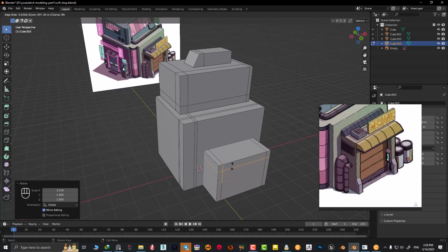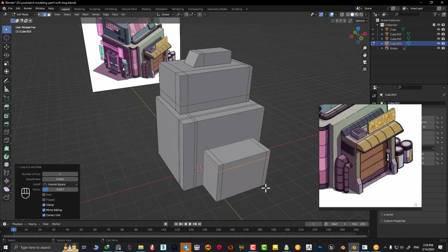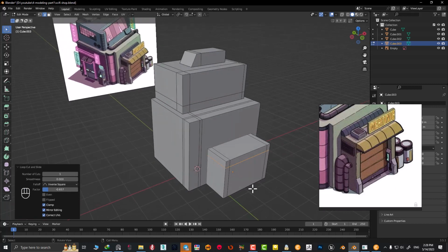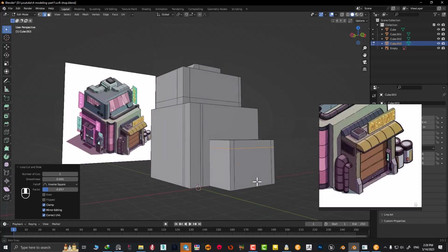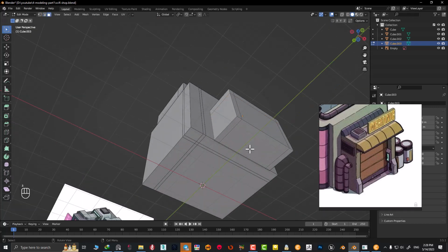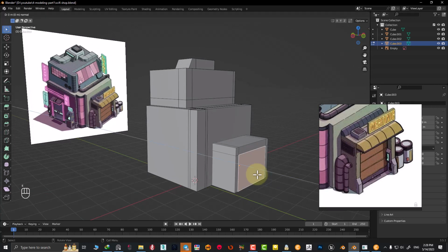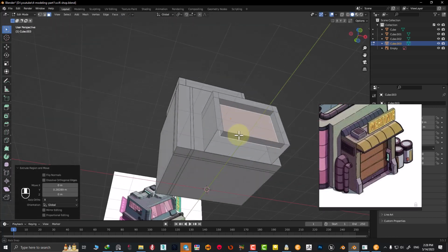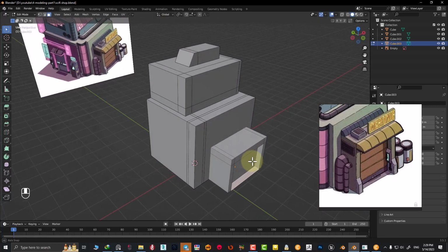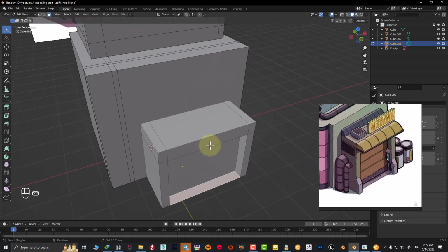Next, we want to remove the faces at the bottom because we don't need them. To do this, press 3 at the top of your keyboard to select polygons. Hold Shift and select polygons that we need. Press the delete button and select face. Now choose the polygon you want to work with and press E followed by Y to extrude it in the Y direction. After that, delete the extra polygon you created.